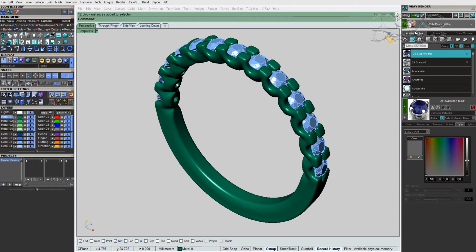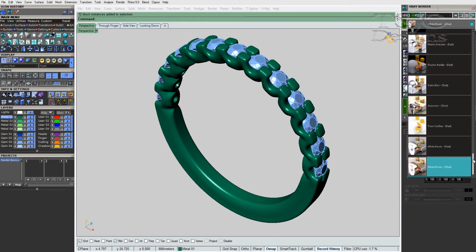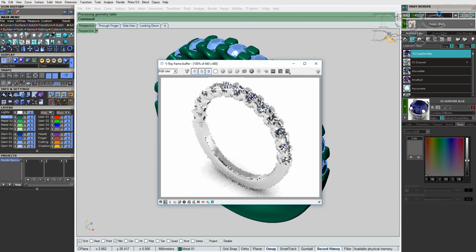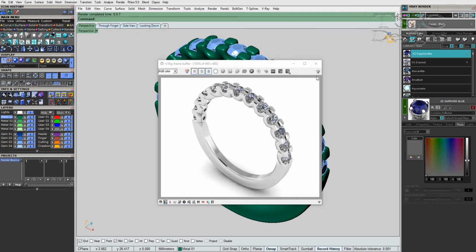So getting back to the rendering, let's start with the very basics. Classic fast. These styles are predetermined parameters: lighting, HDRI, high dynamic range, something or other. I don't remember it, and if I don't remember it, I'm not interested. So we're going to apply this scene and click render. Leave it on the 640 by 480. This is good for previewing for yourself. So if you're on the right track, it renders the quickest.